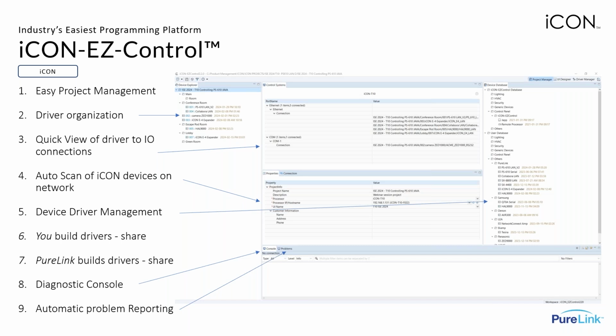And the problems tab is what we talked about earlier, which is our easy debugging option. It doesn't allow you to go about your project if there are any errors that would prevent it from running properly once uploaded to your touch panel. So that gives you the option to go directly to the line of code that is improperly being read, whether it is JavaScript or easy language.